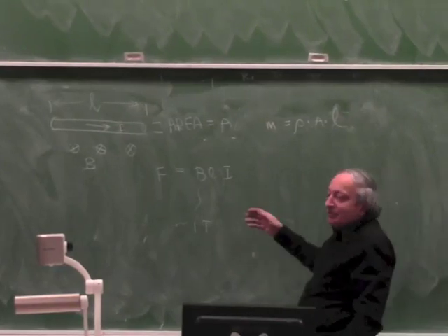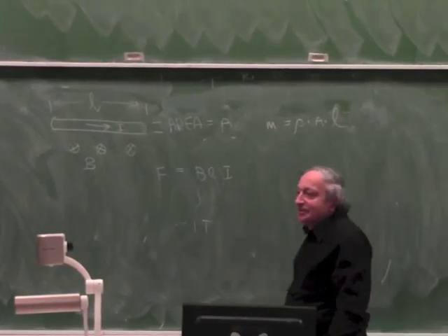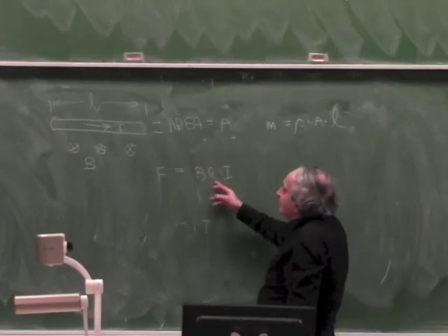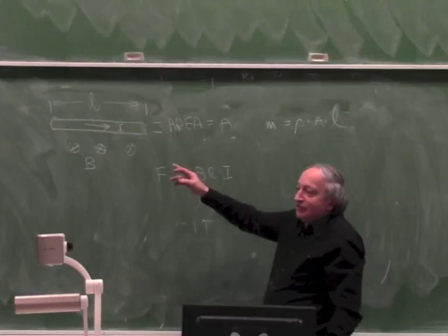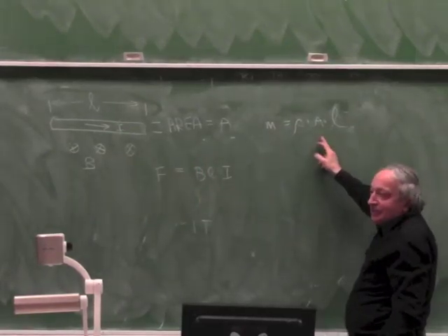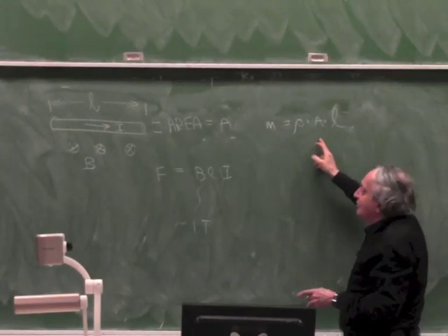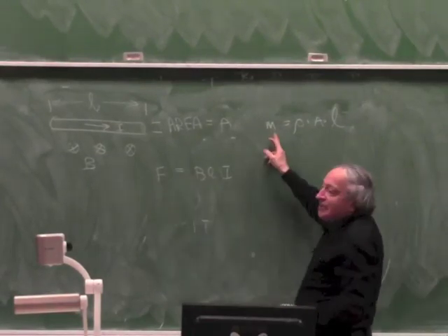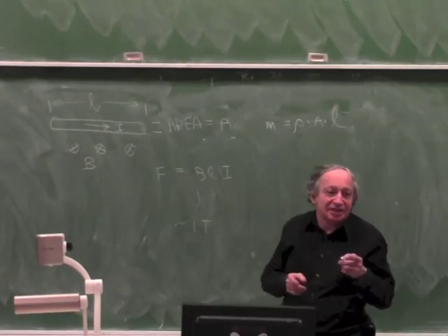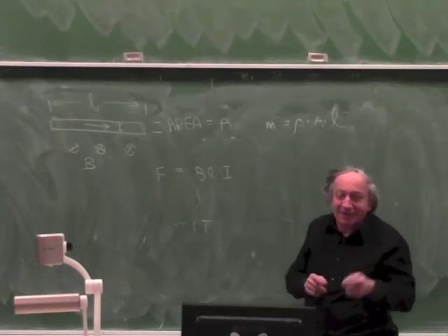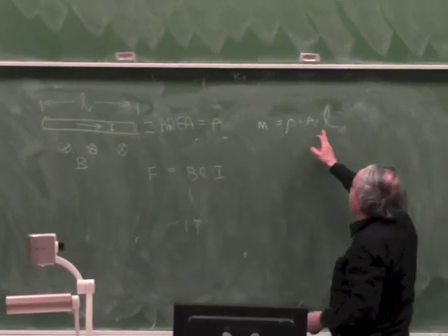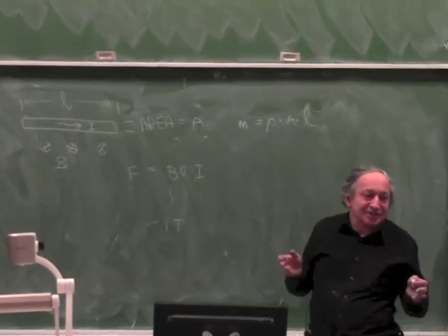And you can bet on it that they optimized it to this. Okay, so B is fixed. L, you can increase L, but if you increase L, the mass will also get bigger. And you can already see where I'm heading, because I want to derive the force and the mass and divide the force by the mass to get the maximum theoretical acceleration. If I make L bigger, the force will be bigger, but the mass will be bigger by the same ratio, so I don't gain anything.